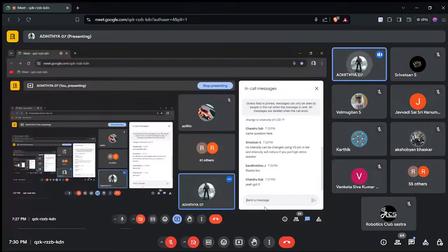In ICs, you will always see one small dot and a divot. Whenever you see an IC, the pin below this small dot will always be pin number 1. It will go from 1, 2, 3, 4, 5, 6, 7, 8. Then it will switch here to 9, 10, 11, 12, 13, 14, 15, and 16. In this IC, the first pin is an enable pin.